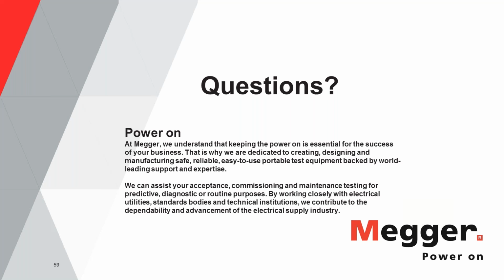The second part of the question is, should you be performing the test at rated voltage and the current required to trip the breaker? That is what we call a factory test. Out in the field, you don't have the luxury of 6,000 amps at 480 volts. That's just going to be a huge amount of power source that you need to have. So typically the test is performed at high current and less voltage.